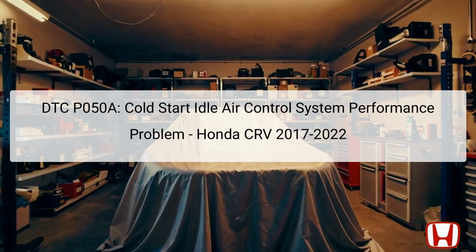The IAC controls the amount of air that bypasses the throttle plate, helping the engine maintain smooth operation at idle, especially when starting cold. Affected components include the throttle body, mass airflow MAF sensor, IAT intake air temperature sensor, and various ducting that directs air into the engine. Understanding the interrelation of these components is vital for effective troubleshooting and repair.